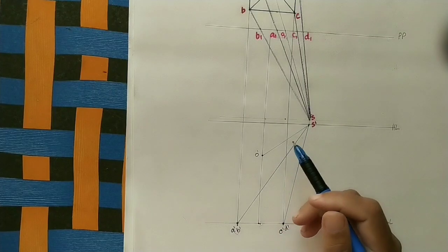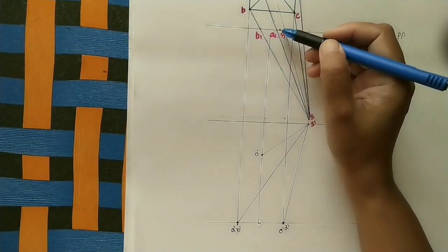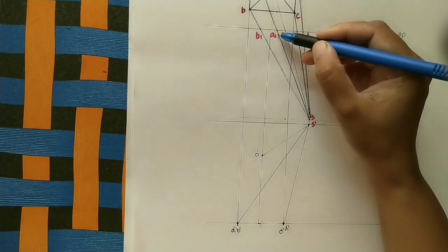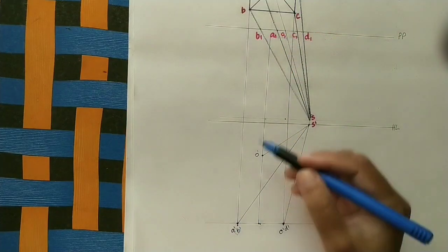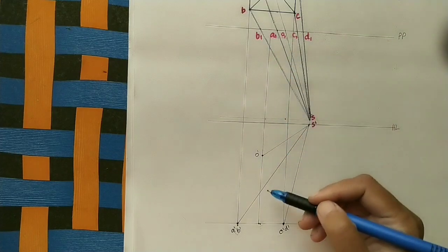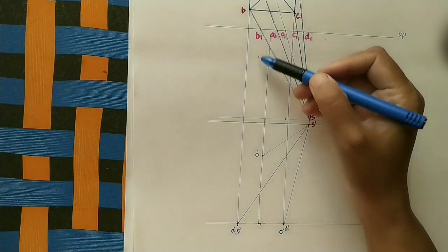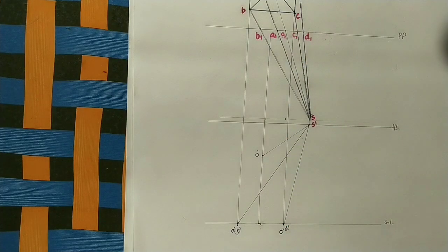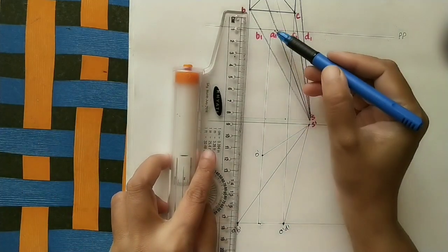Now for doing the perspective view, wherever intersection points are there, from A1, B1, C1, D1 like that, just do the projector line from A1 up to the A inclined line, from the A inclined line here to the A inclined line this side. Similarly from B to the B inclined line, from C to C, D to D like that. We will get the vertical projector lines. Let us start from A.